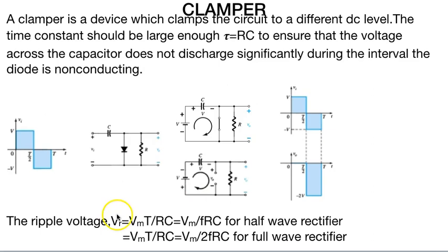So if you see this input signal passed through this particular circuit, you will see that the positive voltage, plus minus voltage, will charge the capacitor to the plus minus voltage itself, and the diode will be short circuited at this point of time. No voltage will be there on the output because no current is passing through the resistor at this point of time.